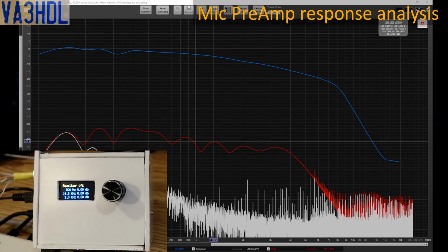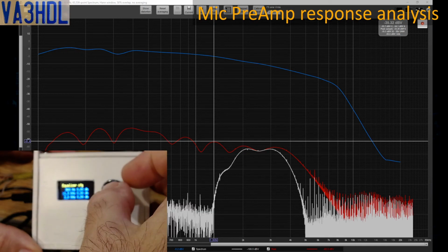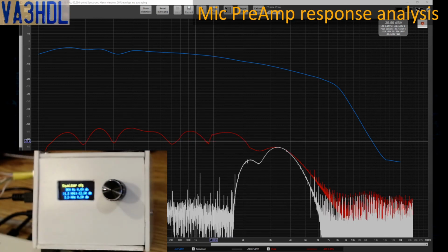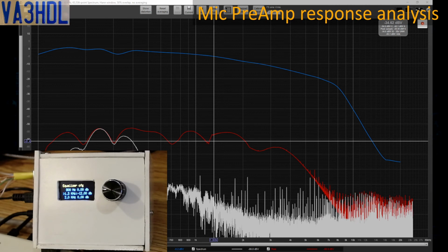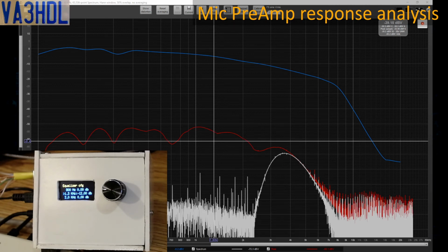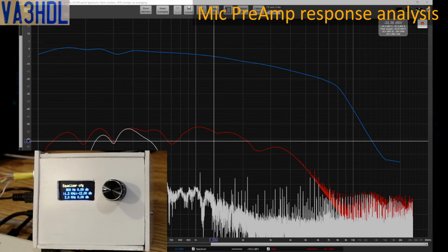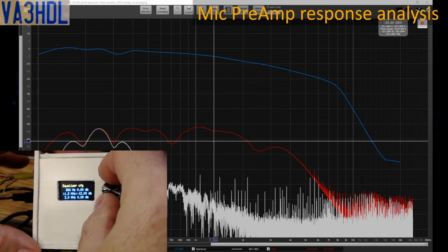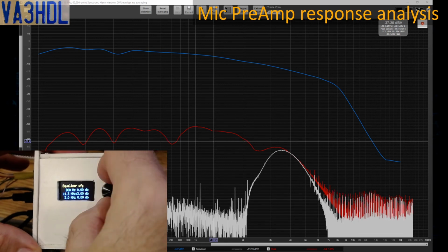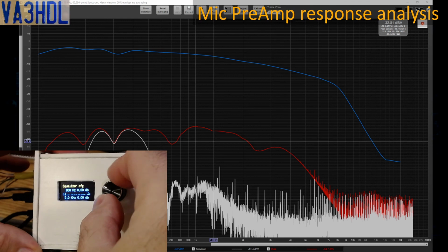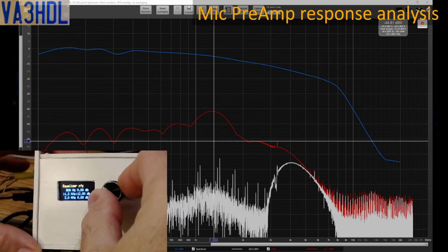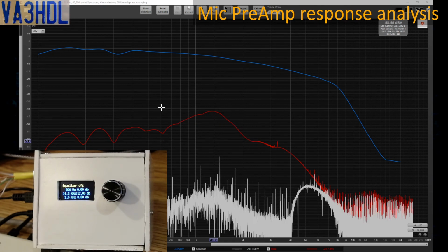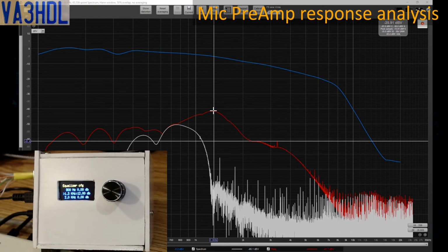Now in this particular test, I start the sweep with the equalizer on. And this is a custom sweep for the entire audio band that goes from 100 Hertz to 20 kilohertz. I'm focusing on the 1.3 kilohertz frequency. At that point, I move from minus 12 to plus 12 dB to show the response on that particular segment of the equalizer. As you can see on the screen, the peaks increase at that particular 1.3 kilohertz frequency.